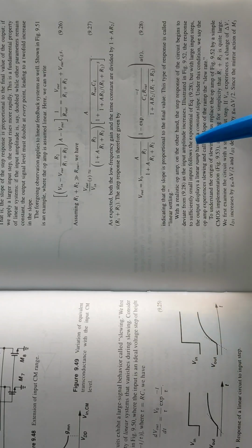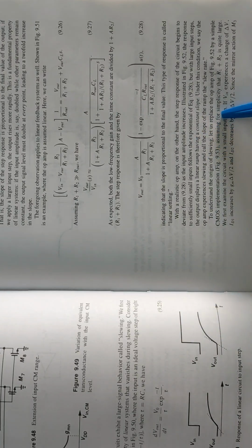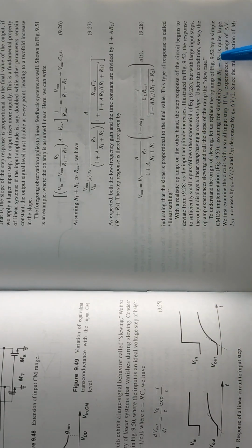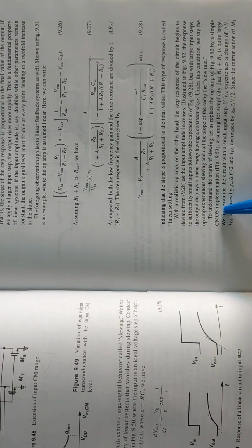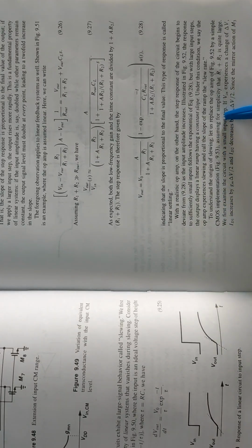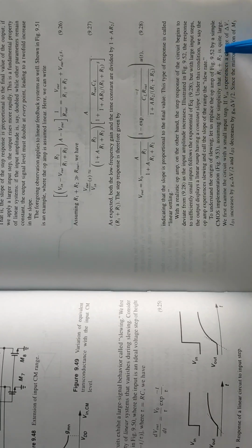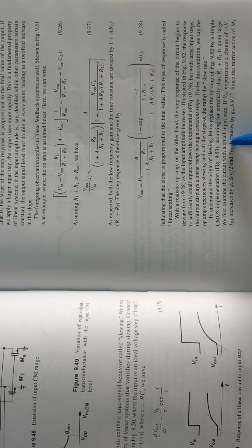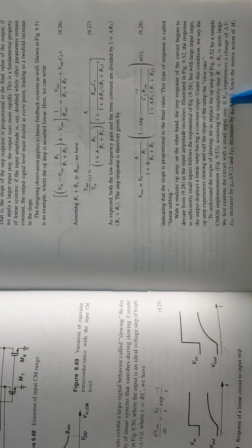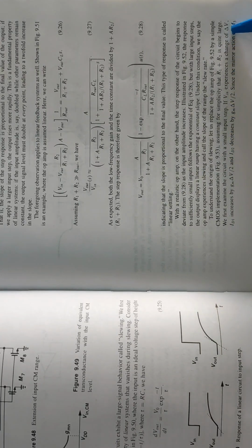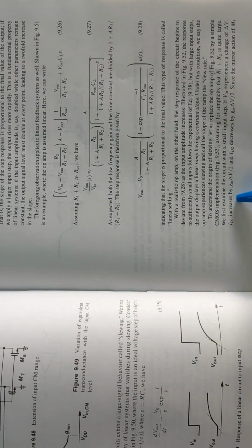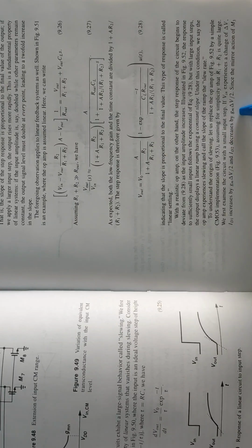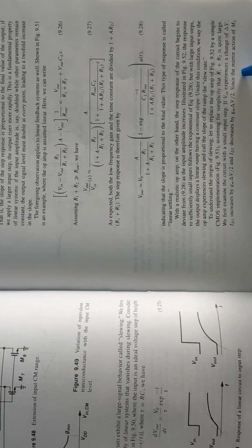To understand the origin of slewing, let us replace the op-amp of the figure by a simple CMOS implementation, assuming for simplicity that R1 plus R2 is quite large. We first examine the circuit with a small input step. If Vin experiences a change of delta V, ID1 increases by gm delta V by 2 and ID2 decreases by gm delta V by 2. Since the mirror action of M3